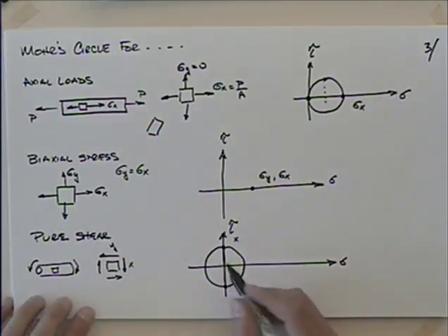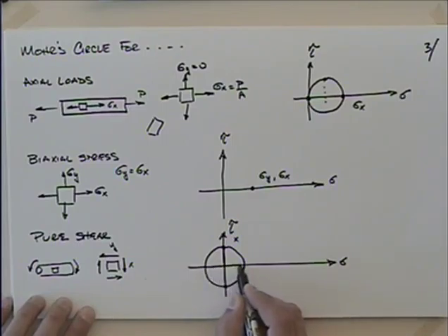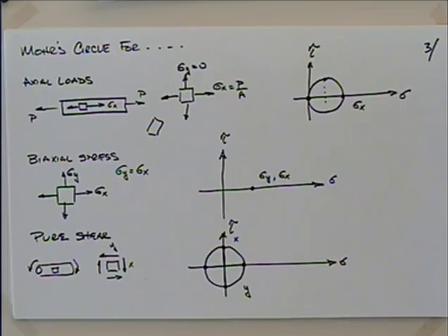And with pure shear, if we rotated that over to here, did we get some maximum value for tension? We did, didn't we? And that's where we saw this crack on here at 45 degrees. You might say, well, there's 90 degrees there, but remember the angle on Mohr's circle, we divide that by 2, and we look at the angle on the element. That's why when we were taking that chalk and twisting it, we got that fracture at that classic 45 degrees.